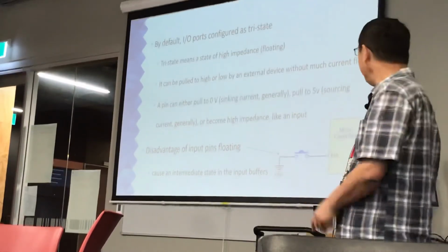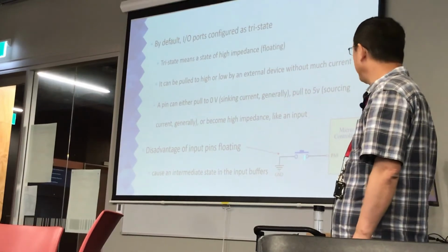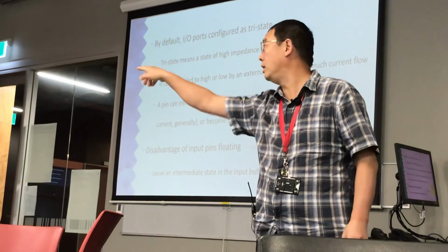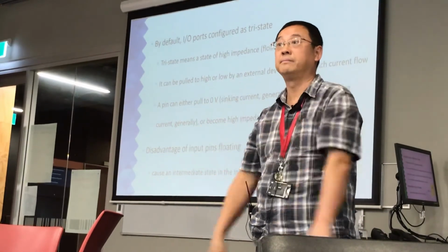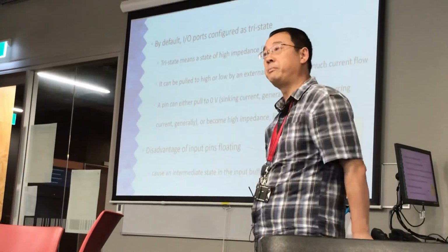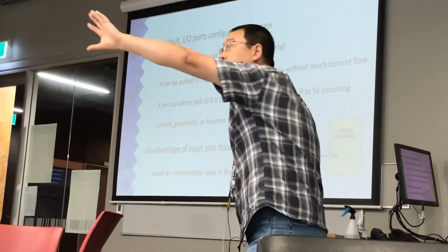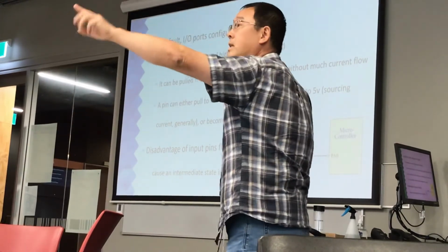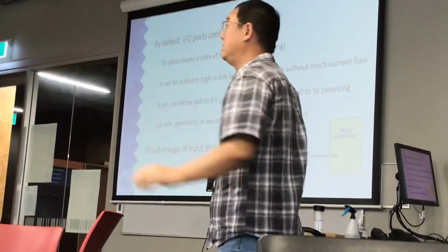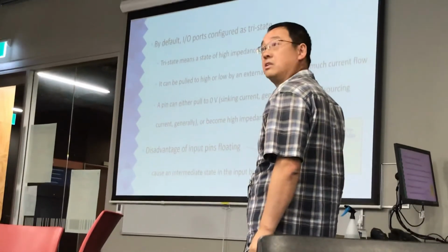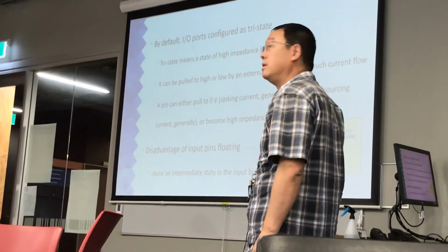For example, if I use this push button to turn on a big motor to drive something, and somebody is servicing the PCB and by accident a finger touches it, a little bit of static can change the whole state.